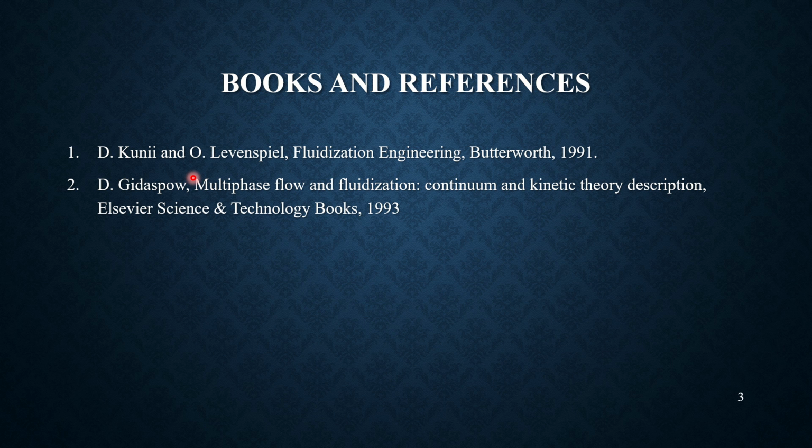And next is Gidaspow's Multiphase Flow and Fluidization: Continuum and Kinetic Theory Descriptions. As I have already told you before, the modeling of fluidized beds can be made under two categories. For the fluid phase we would be using the continuum theory, but for the solid phase we can either go with the continuum theory description or the Lagrangian, where in the Lagrangian we track each individual particle. That is the complete mechanism, the true mechanism happening inside the system, whereas for the sake of easing the model, we go for the continuum theory description.